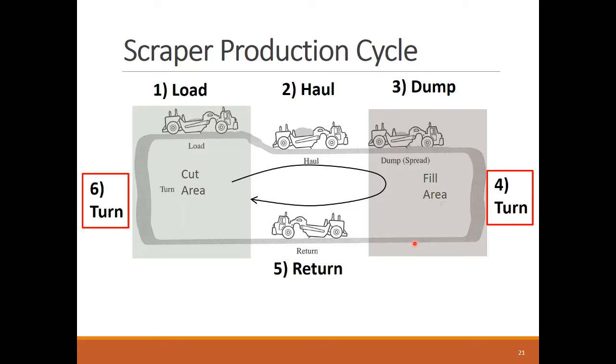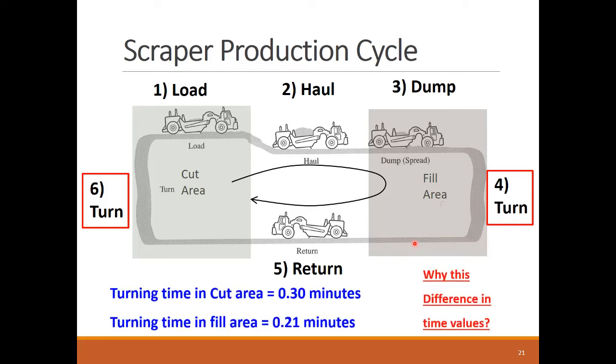Lastly, the two turning times are estimated based on the site conditions. But here are some suggested values for turning times at the cut and fill areas. More time is estimated for the cut area turning because the scraper spends more time adjusting to the desired cut lane, and also waiting for a dozer to push it in the pusher-loaded scraper operation, like we'll see very soon.